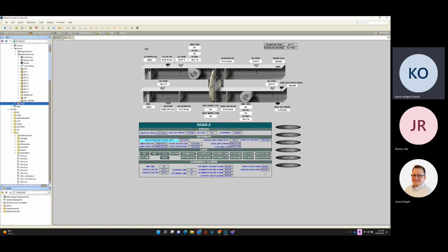Is that correct? Essentially, what I'm trying to say is there's a mismatch between command and status. It goes into a fan alarm. You don't take away the command, right? Right, there's no reset. It's just repair at that point. Correct. Okay. Now, that is a great point.